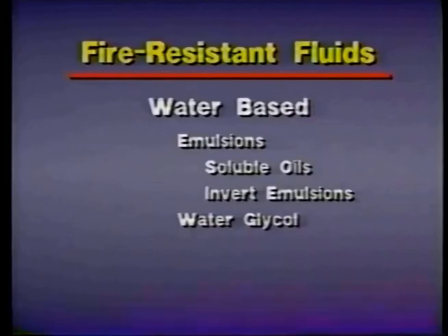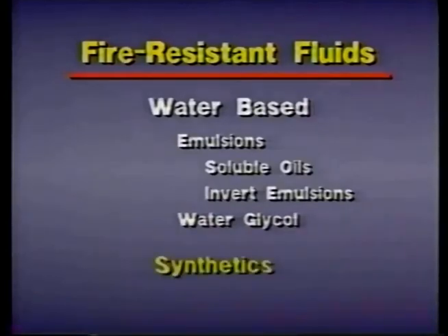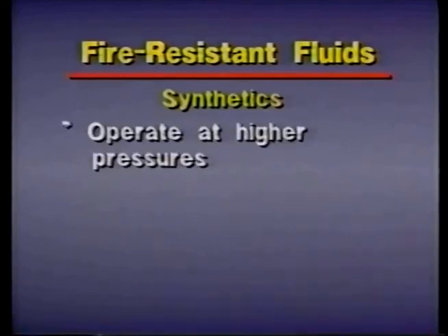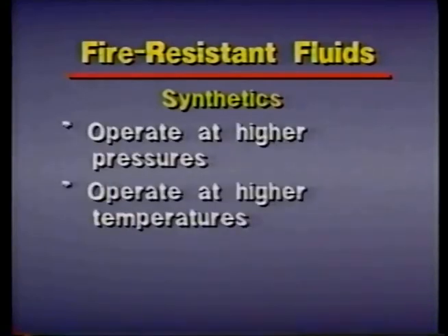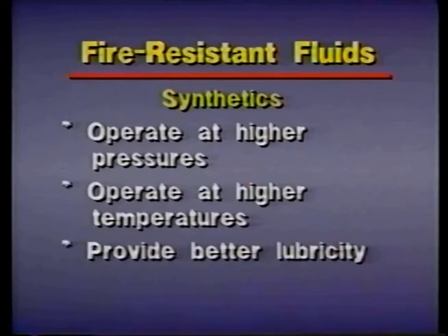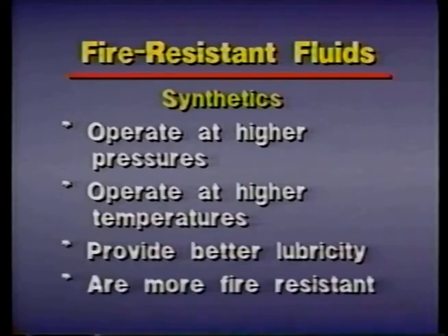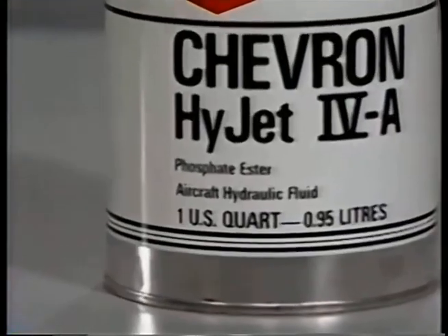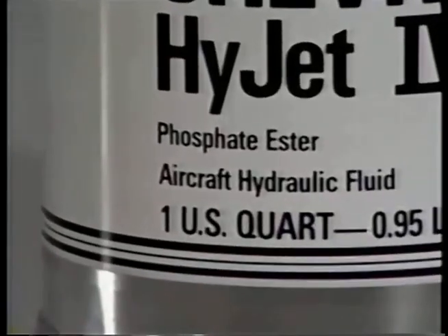The last category of fluids we need to discuss are the synthetic fluids. These man-made solutions operate at higher pressures and higher temperatures. They provide better lubricity and in many instances are more fire-resistant than emulsions. They do, however, cost more than most water-based fluids. One common synthetic fluid is phosphate ester. It is often used in high-pressure systems where fire resistance is needed.